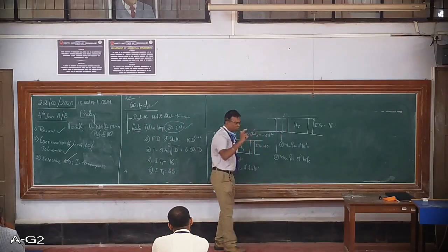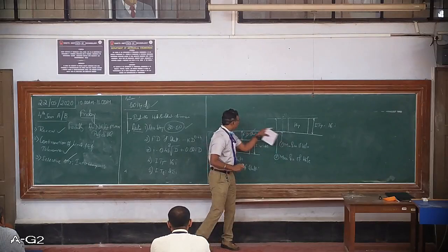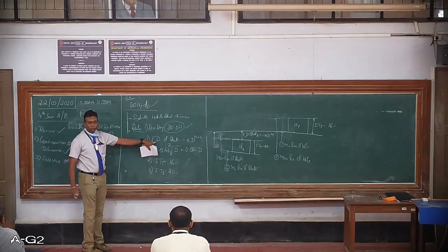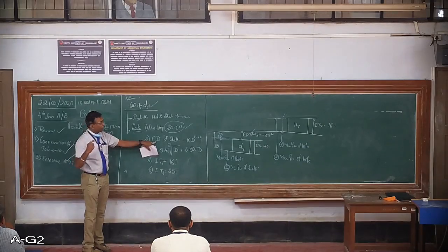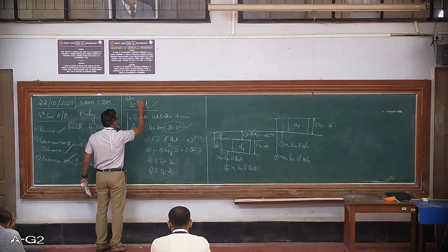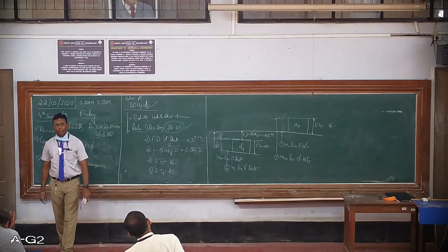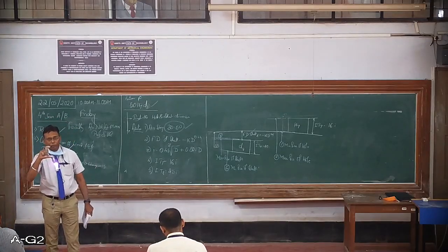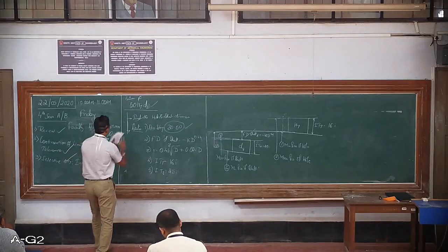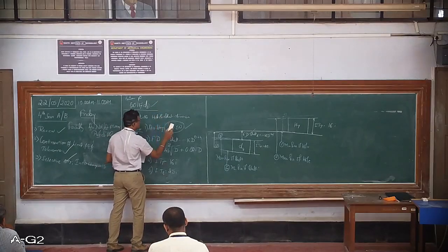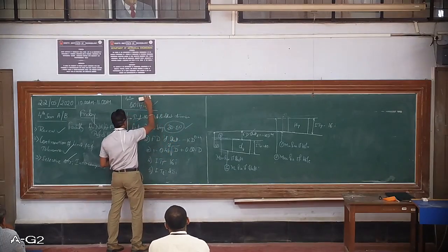For each hole, the fundamental deviation is 0, so that's why you don't see it given. Fundamental deviation for shaft is given, but you are not given the fundamental deviation for hole primarily because each hole has 0. Had it been, let us say, F hole, F7, F5, F8, whatever the value, we would have been given the fundamental deviation for F hole. That will be given in the examination. But most of the numericals will have H because standard practice is to go for the hole based system, and the deviation for holes is 0.